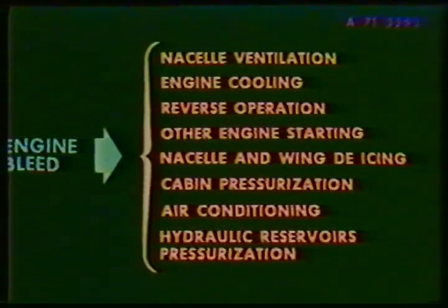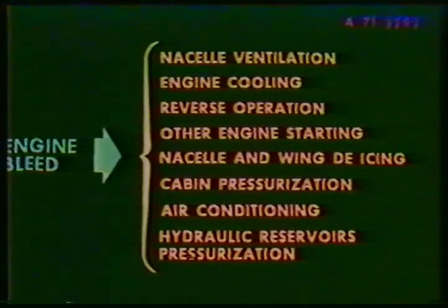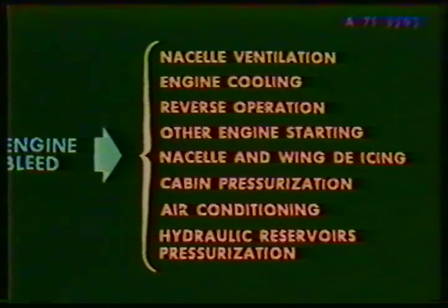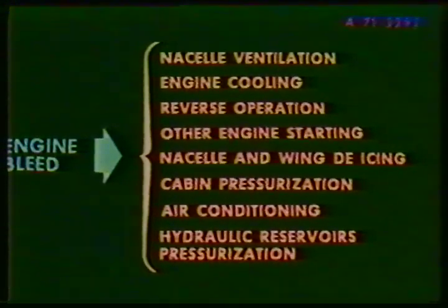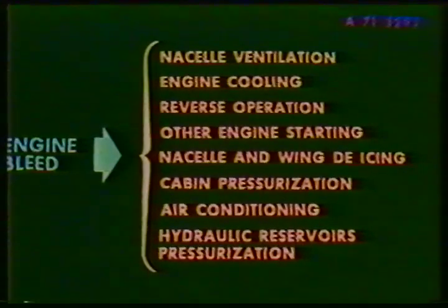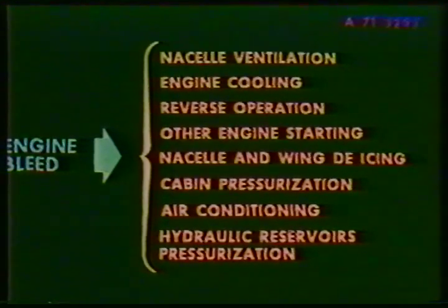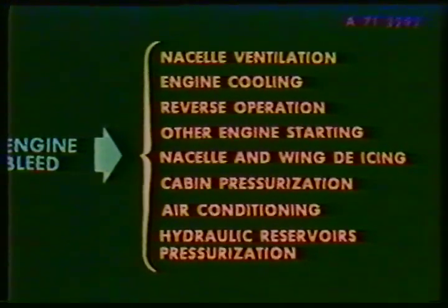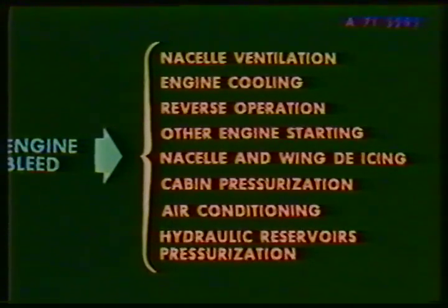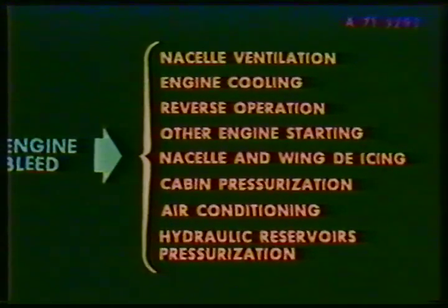Air bleed at various engine stages ensures reverser operation, nacelle and wing de-icing, cabin pressurization, air conditioning and hydraulic reservoir pressurization, and air for cross-bleed engine starts.